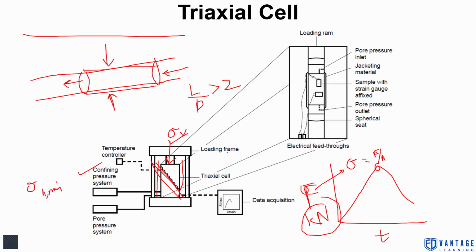So they are standards. And now the main thing is we need to also see the strain, because what Hooke's law states is, for an equivalent amount of stress, there is an equivalent amount of strain also being generated until the body fails, until this point, right? So we can get strain from LVDTs. They are transducers where you have strain gauge affixed. So to see what is the equivalent strain of the body, I'm applying compression, right?